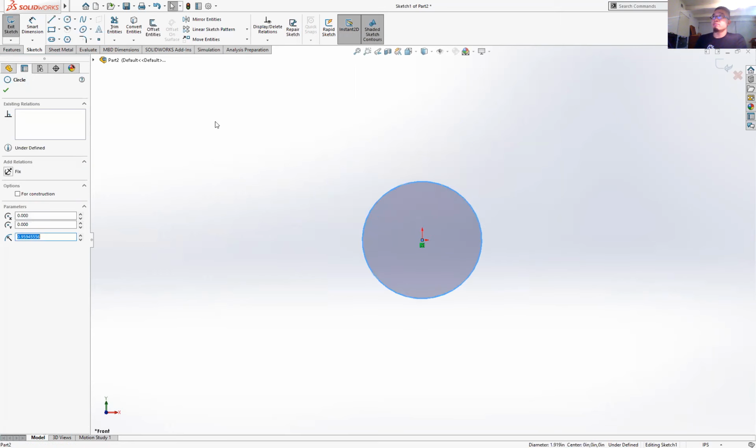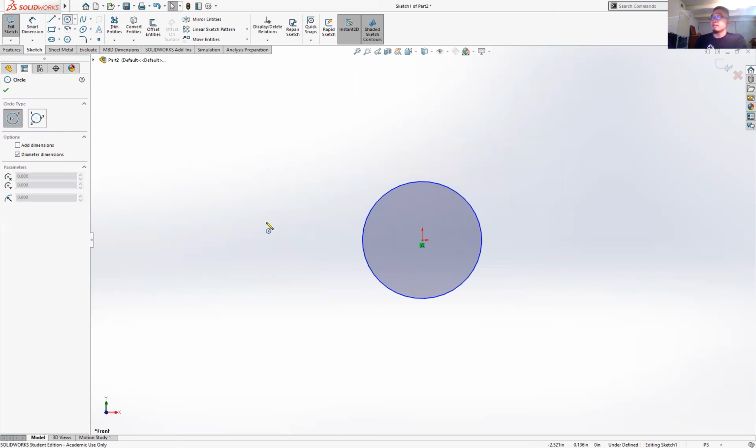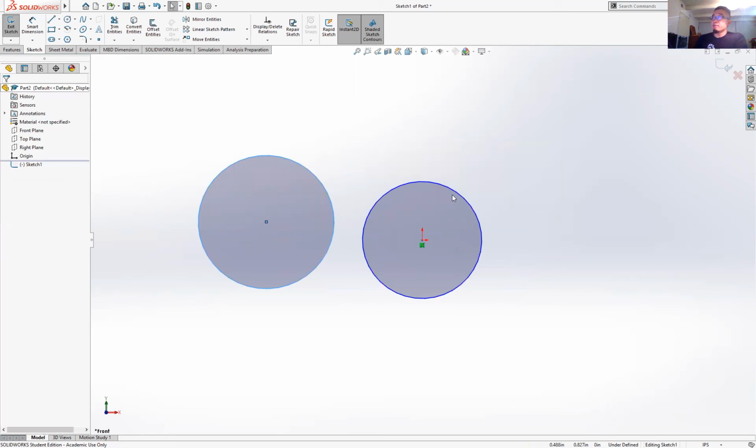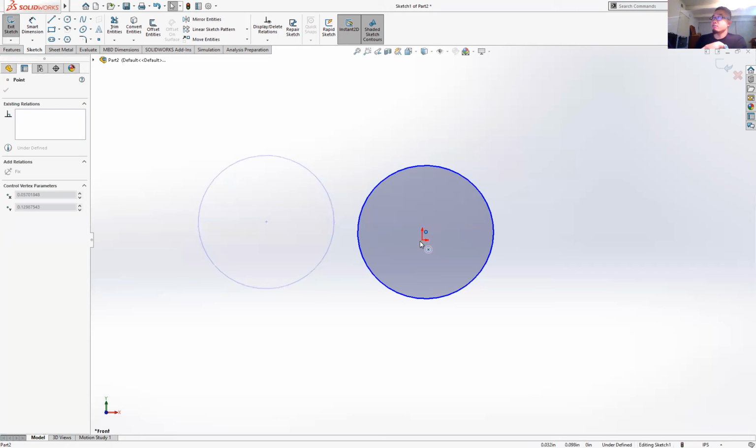Now, let's say you had created a circle and you had not been able to select the origin for some reason. I'm going to delete this one. So select this one, delete it. What would I do? How would I move it to there? Well, there's a few ways. I could grab it and then just drag it onto there and see how it shows up.